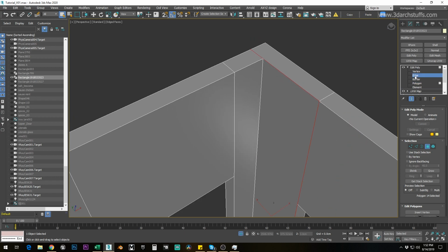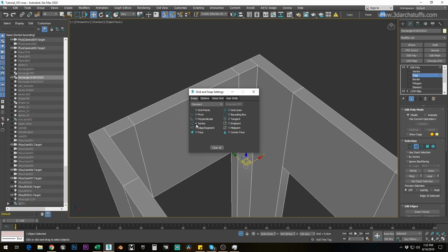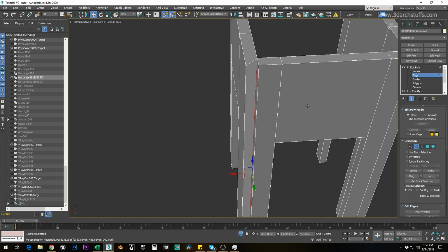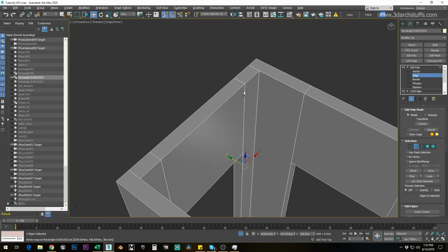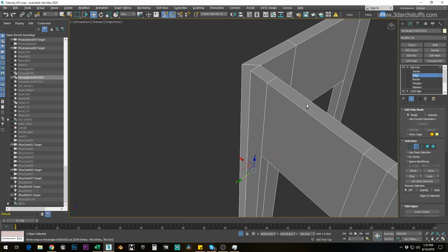If you want to make a very accurate and realistic architectural visualization, then things like this should not happen. You have to go into Edge mode and click this edge, then press S to turn snapping on, making sure it's a 3D snap. Right click here, and in Snap Options click Vertex, and in Options click Snap to Frozen Objects and Translation Enable Axis Constraints. After that you snap it here like this. Every object should be snapped to each other, and no object should be crossing like this.